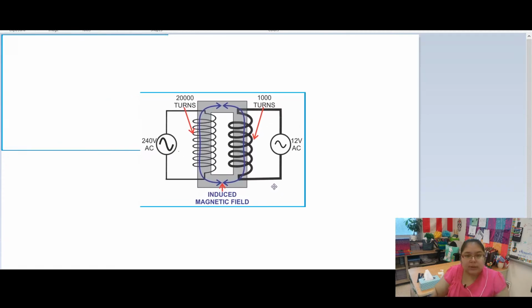Okay, don't bother with the line. Let's see the first part. If I say this is an ideal transformer, 240, I give you the power first. This one is power, this one is current. The current is 2 ampere. So the power should be 240 multiplied by 2, which becomes 480 watt. That is the primary power.